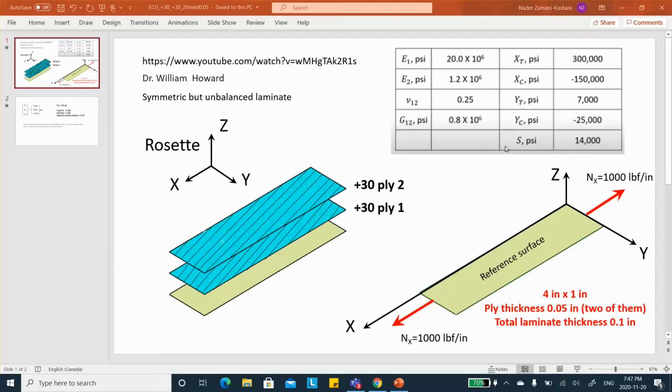The reason was that the shear strength, instead of going in the box which actually specifies it, I put in the wrong box, so shear strength was assumed to be zero, and my numbers were different from the Tsai-Wu and Hoffman numbers from hand calculation. So that's taken care of.